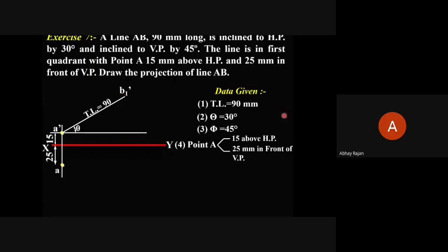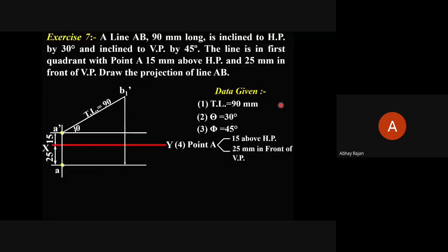Good, good. So we are going to do that. Drop it likewise, and once you draw a parallel line through A, you are going to get the top view of this line inclined to HP by 30 degrees. So this is your first case. You name that point B1, since this is our first assumption.